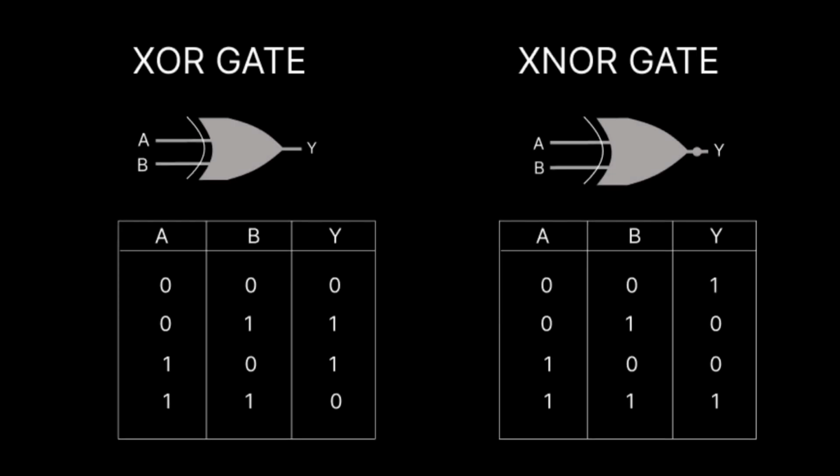And we see that where the XOR produced a 0, the XNOR produces a 1. Where the XOR produced a 1, the XNOR produces a 0. You can also notice the same property, but now inverse in the XNOR gate. It produces a 1 when both of the inputs are the same, but it produces a 0 when both inputs are different. Now we can see a pattern happening here, and we'll explore more in the future about it.